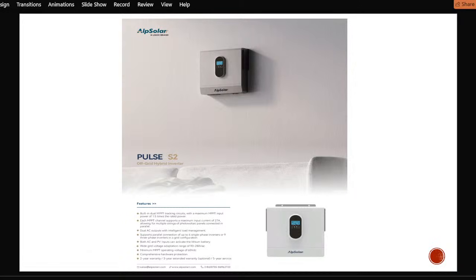Its maximum charge and discharge current is from 150 to 220 amps. You can see that with this, you can charge your battery as fast as possible and still feed the large and industrial loads that you have in the house. Yes, it also wakes up your battery, like I said. Now for the individual MPPT of this 16 kilowatts, it has as much as 8,250 watts for each of them. So that's a whopping 16,500 that you can get from this. Everybody say that's massive.